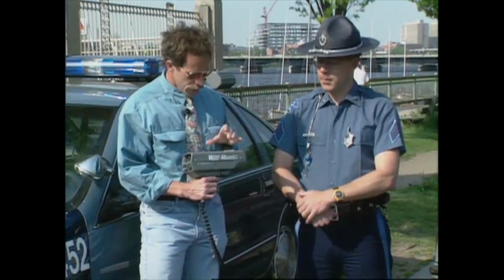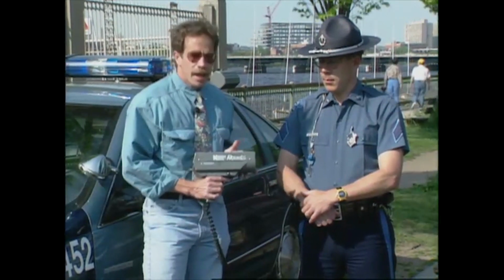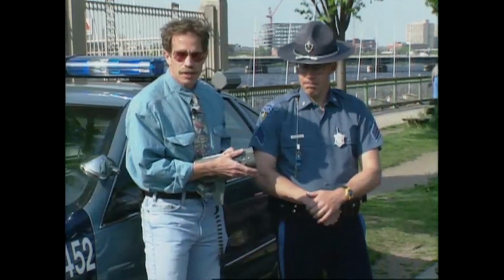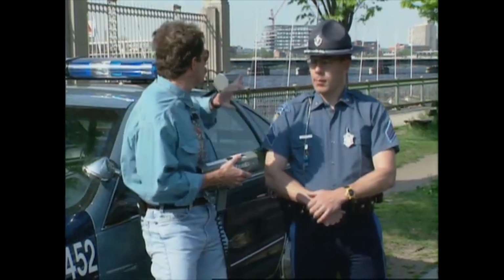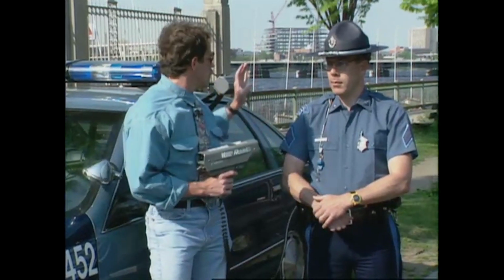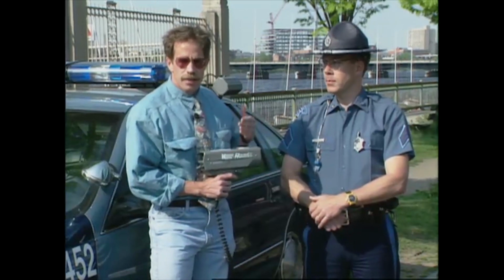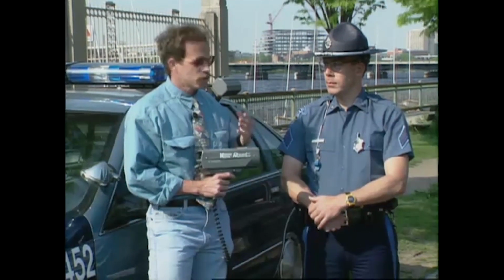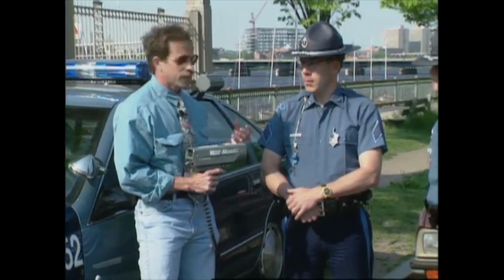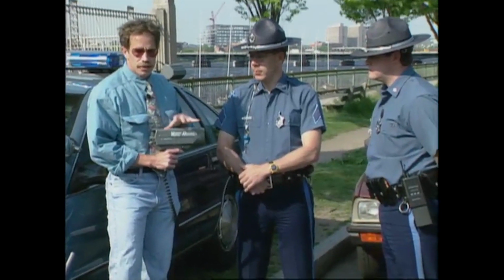So what the unit does is very carefully compare the outgoing frequency to the return frequency and then measure speed. Now, there is a little bit of a problem with this unit in that it's got a fairly wide beam. The beam width is about 12 degrees, so it sort of sprays out over the whole road. That's okay, because it'll lock onto the largest signal that's returning. That'll either be the closest vehicle, or in some cases the biggest vehicle. If you have a bus or something like that, you'll get a large radar return. But it's a very good unit.